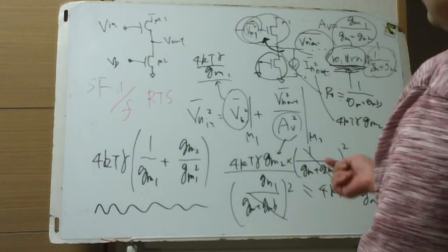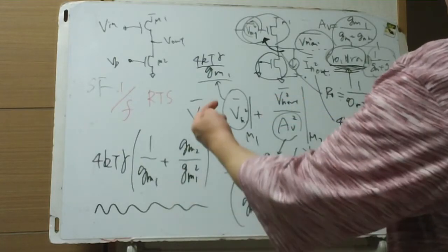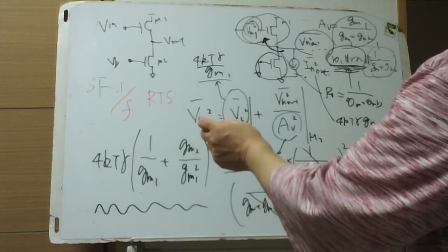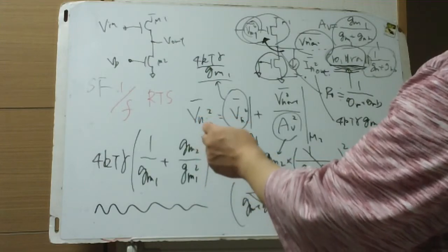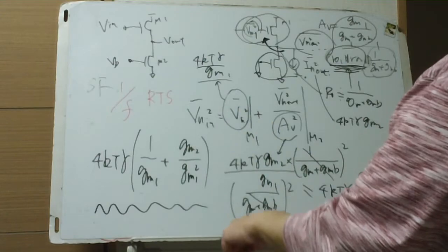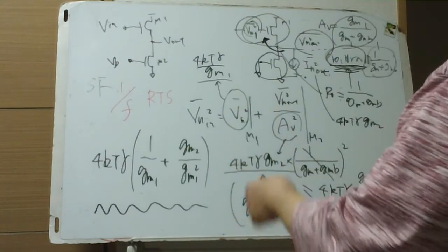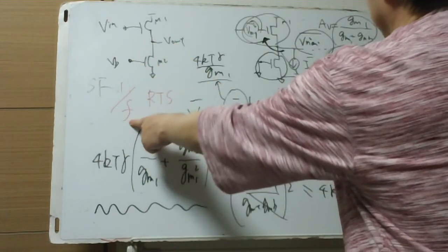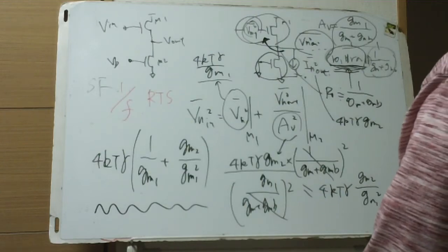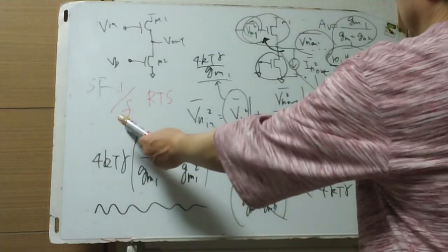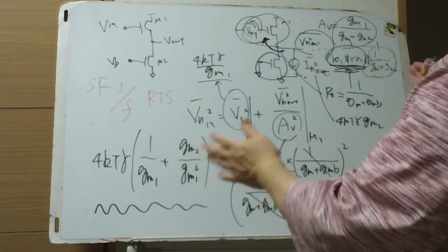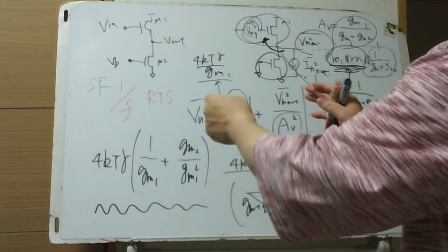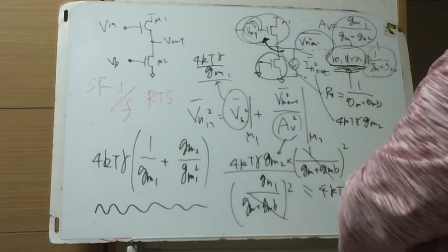The electron jumps into the oxide at some period, and back to the channel randomly, and this is integrated to 1/f noise. The noise is inversely proportional to frequency: the higher the frequency, the smaller the noise.